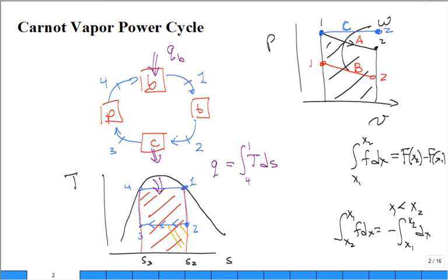This, which I'm just visibly seeing the magnitude of the area, from 2 to 3, the area under that curve, that's out of the system. The difference is, what's the difference? What's enclosed by the cycle? What's enclosed in the box? And so the Q net is Q boiler plus Q condenser, where this is going to be a negative amount.